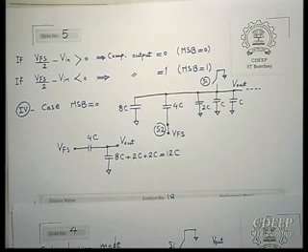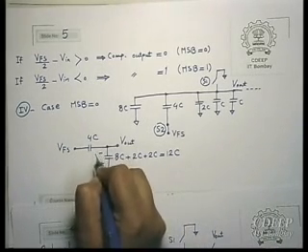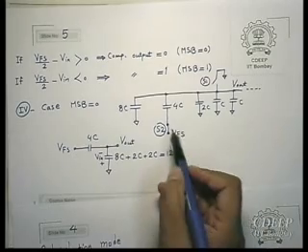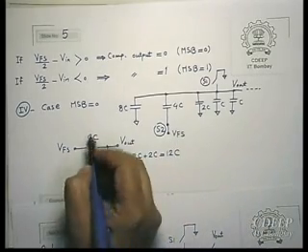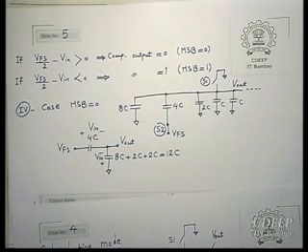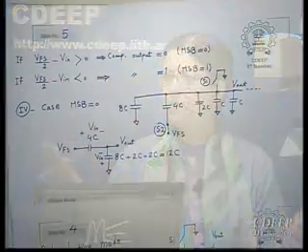Now look at the distribution of V in. Again, you have this V in on all capacitors, and for 4C, because the bottom plate is connected to V full scale, this is V in. Again, if you notice, there is no change in the total voltage across these two capacitors, 4C and 12C, due to V in. Therefore, there is no change there.